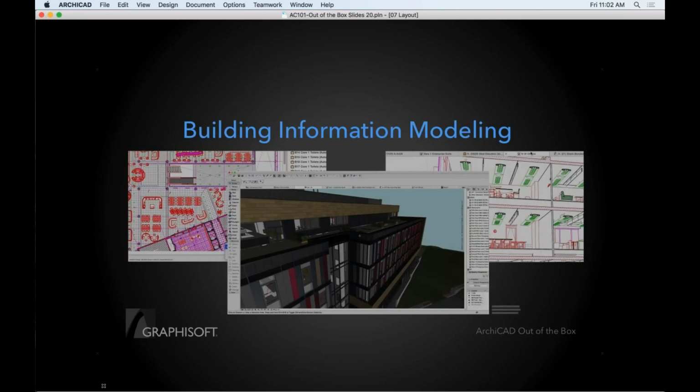At the core of everything, though, ARCHICAD is a BIM tool, or Building Information Modeling, as I'm sure you've heard that term before. The key thing about this is that you are creating a virtual model within the computer to simulate the actual construction in real life. Because of that, you can slice this model to get your drawings, your floor plans, sections, elevations, details, etc. And anytime you update the model, it changes everywhere amongst all of your drawings. So they're all coordinated.